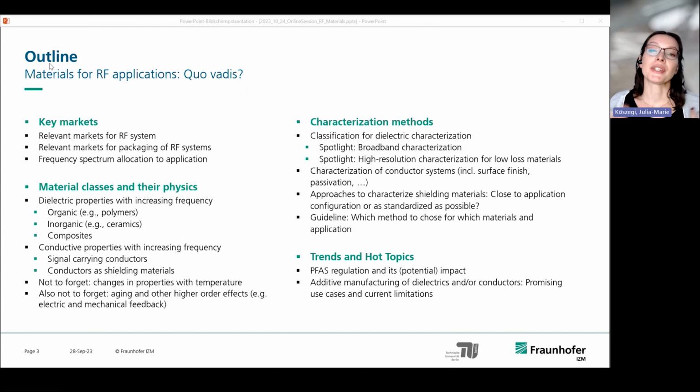So we need to understand the materials from the physics of the build-up, starting with the dielectrics, for example, organic, inorganic, composites, then the conductive material. I also started to explain that. And what we should not forget is that all of these material properties are depending on temperature. And even further, today I will show one of our studies where we looked at aging effects and dielectric substrates. So it's not just that the properties change with temperature, but also with duration. So when you keep it at elevated temperatures over time, you will see drifts in the material properties.